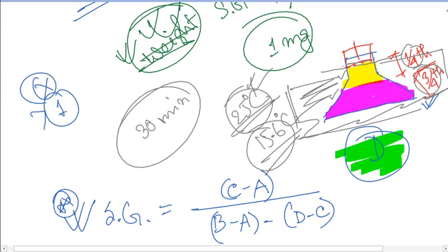There might be a possibility that this material is lighter than the water, so the specific gravity is less than 1. This is also possible. If the specific gravity is less than 1, the water might go underneath it and the sample will be floating in the water.